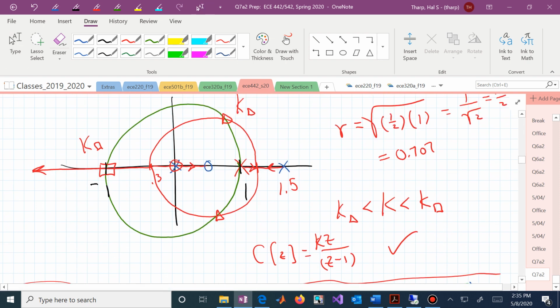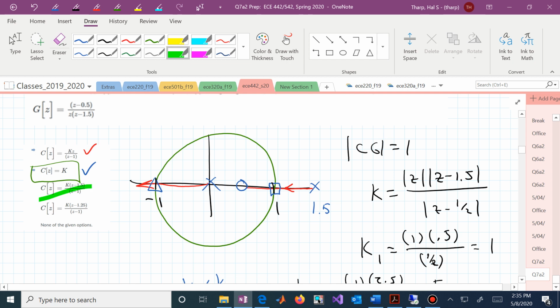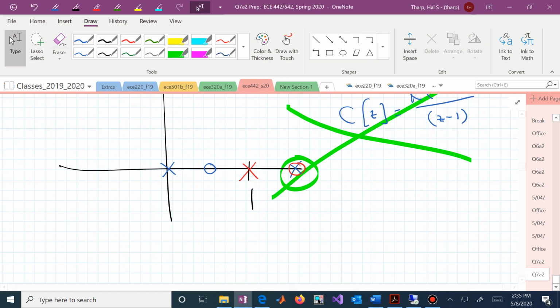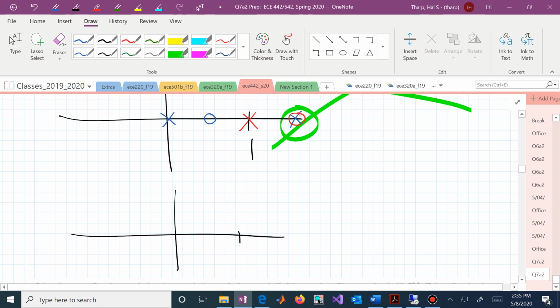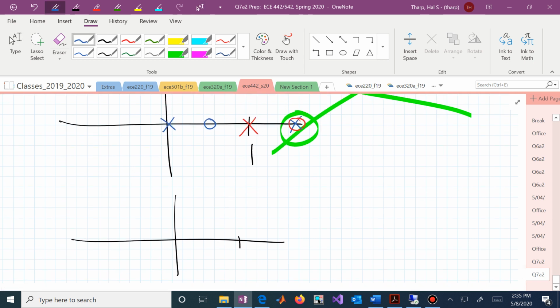That is unstable because in your internal stability argument you will find that you do have a closed loop pole maybe between your disturbance and the output at 1.5. So that's not going to work. You don't even have to do anymore. You can just say, oh, they're trying to do an unstable pole zero cancellation. That's not allowed, so I'm not going to go any further.